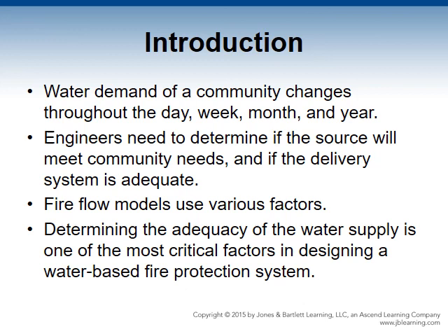Needed fire flow: the number of gallons per minute the fire department will need at a particular location to fight a fire. It is not a measurement of water needed for a fire suppression system. The fire flow models use various factors, including type of construction, size of the structure, occupancy conditions, communication between buildings, and of course, exposures.